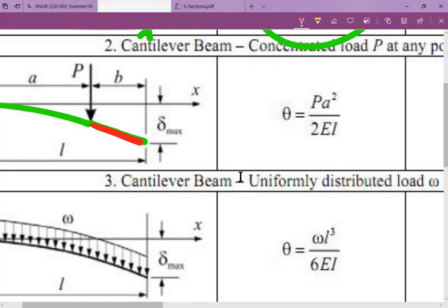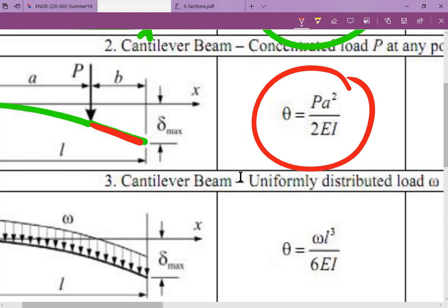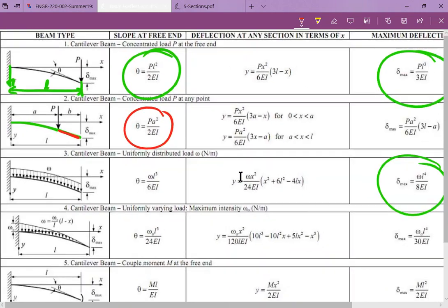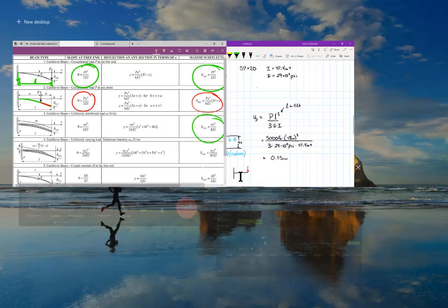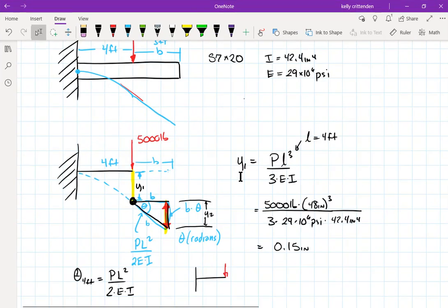That's how we solve it on any of the exam problems. If that problem shows up, we treat the red part as a linear slope, a constant slope, and we treat the constant slope as whatever it was at the end of that A section of the beam. And they may or may not be doing that with this particular chart. So if you try to do web work problems and you use this for one of these problems, I'm not certain it will give you the exact same answer as the process that we did here.